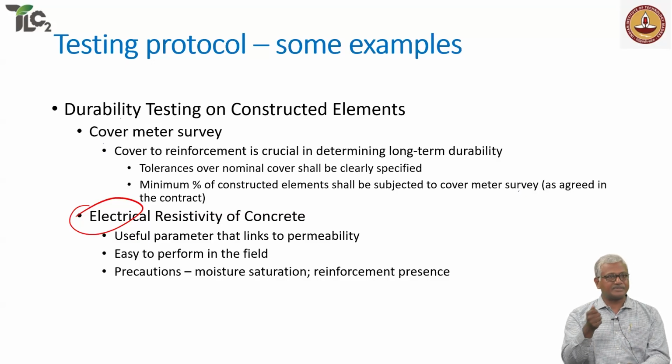There are handheld resistance meters available. In fact, we have a startup from our research park which is also making one such equipment. All of you who are going to be in practice, I urge you to make use of that equipment and look at the quality of the concrete through a durability perspective also.